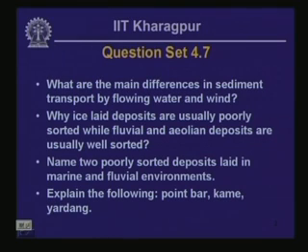The first question was, what are the main differences in sediment transport by flowing water and wind? So the essential difference: the basic processes involved in sediment transport by both water and wind are quite similar, but the basic difference arises because the buoyant weight of the sediment particles transported by these agents varies quite a bit, because the unit weight under ambient conditions of air is about 1/1000th of that of water.